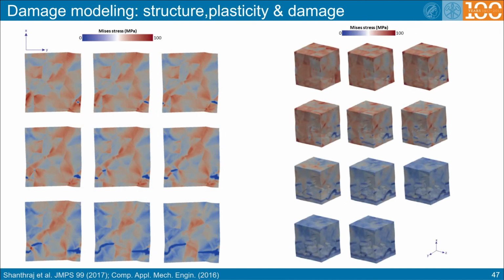We have also modified the software in the direction to consider a corresponding variation of the Allen-Cahn theory that is capable of simulating the gradual evolution of damage out of the microstructure. That is shown here in 2D and 3D sections, where you see how damage is evolving here out of the martensite fracture, then evolving and growing inside of the ferrite material, as you see here, until it starts really percolating through the material. And this is a 3D view of such results. So that means we are now capable in DAMASK to predict the local evolution of microstructurally initiated damage in complex engineering materials.